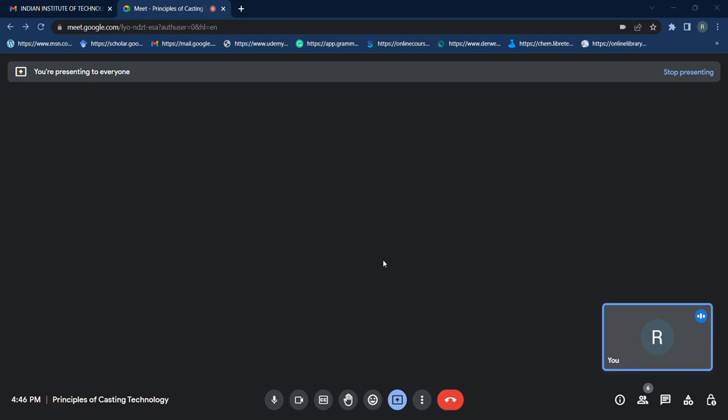So the volume of the riser will be pi by 4 d cube, assuming that h is equal to d. I can calculate the volume of the riser in terms of diameter, and I'm writing it as 0.25 pi d cube. Okay, it's not a big thing.